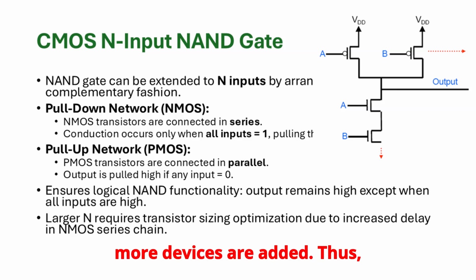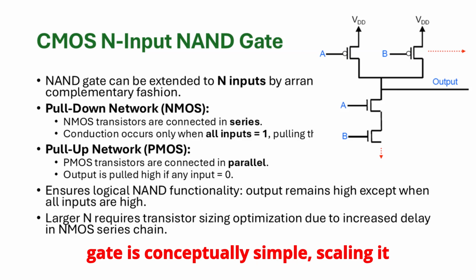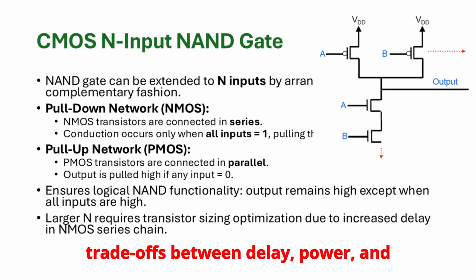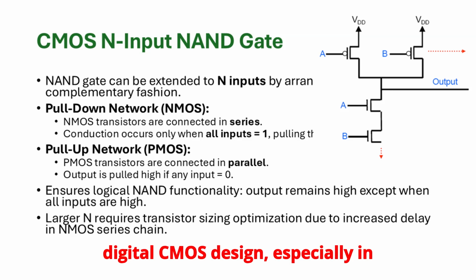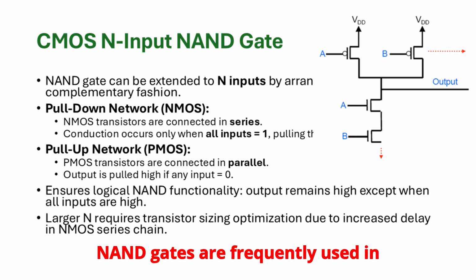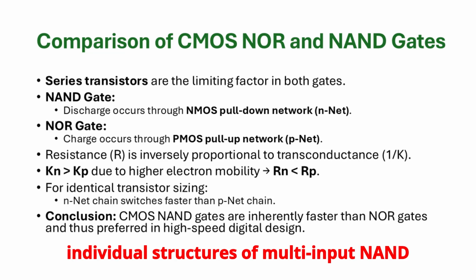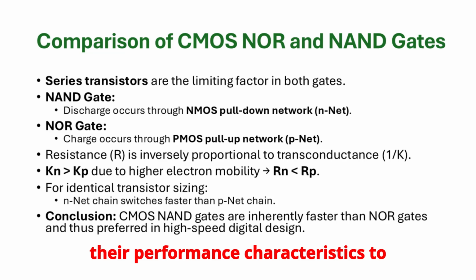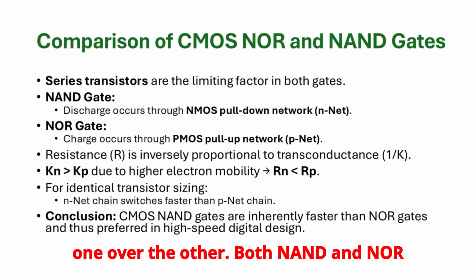Thus, while the logical structure of the NAND gate is conceptually simple, scaling it to higher input counts requires careful trade-offs between delay, power, and area. This is a critical aspect of digital CMOS design, especially in complex logic circuits where multi-input NAND gates are frequently used in synthesis. Having analyzed the individual structures of multi-input NAND and NOR gates, it is important to compare their performance characteristics to understand why designers tend to favor one over the other.